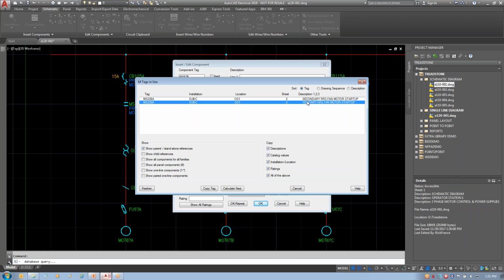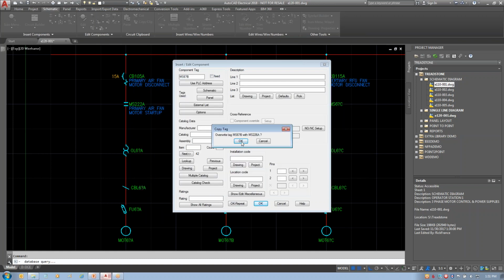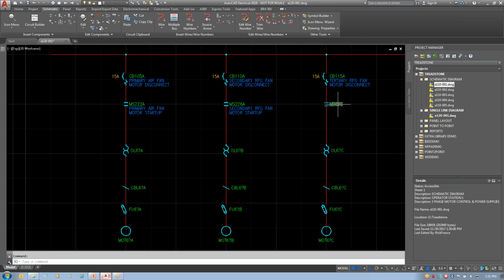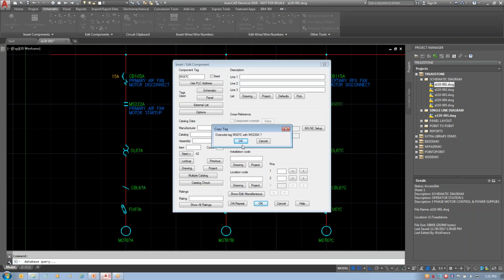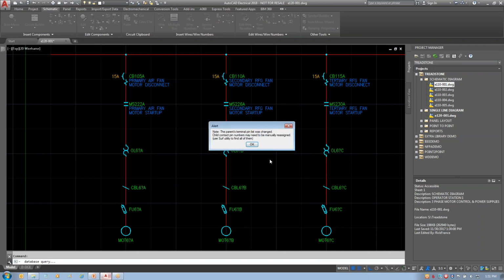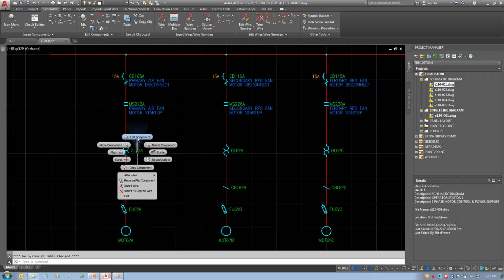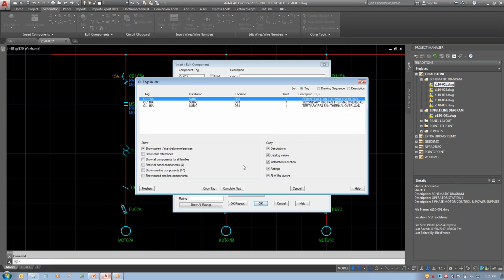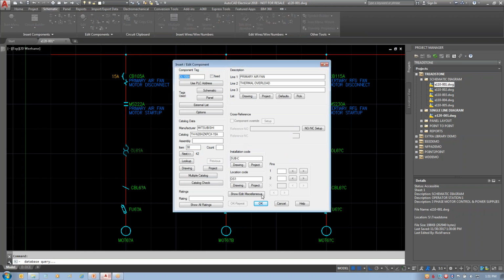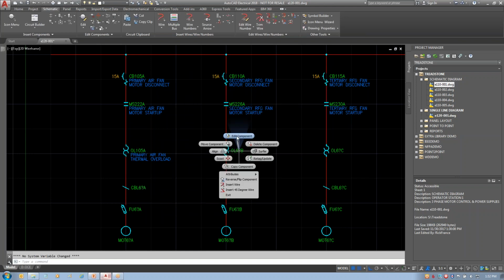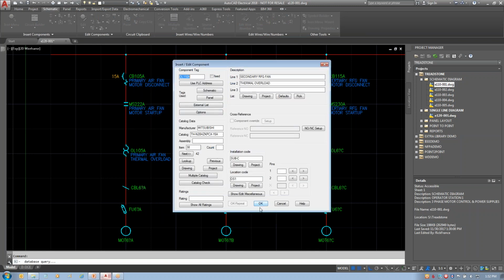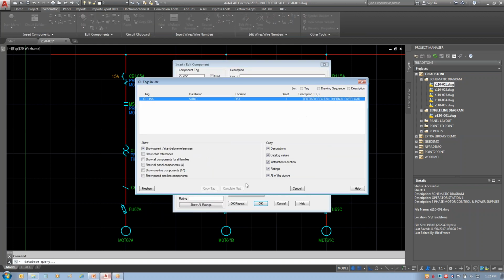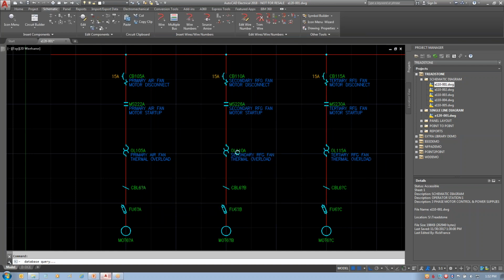As you can see, it doesn't take a lot of time. It's just making sure you select each of the right components that you're connecting up to. It's just a little bit of extra work that is well worth it, because I guarantee you I can connect these up faster like this than I could have added all that catalog information, the descriptions, everything that would have been involved in creating this as a standalone would have been a lot more time consuming than what it's taken me to go through here and just pick these, hit schematic, select the correct one, copy tag, okay, and move on.